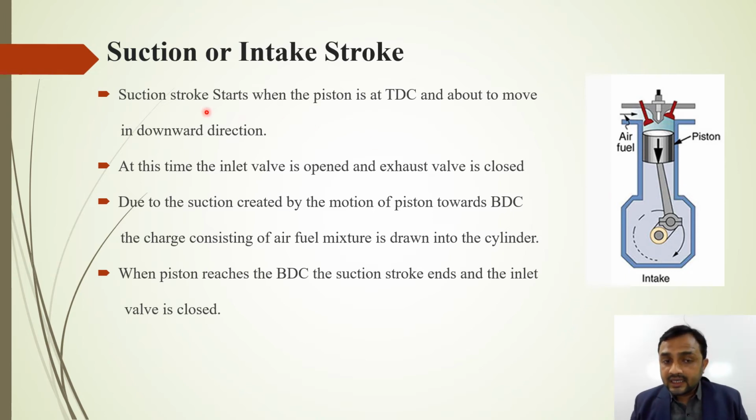In the suction stroke, the piston is at TDC, here, and about to move in the downward direction, towards the BDC. At this time the inlet valve is open, and the exhaust valve remains closed. This is the exhaust valve, closed during the suction or intake stroke. Third point: due to the suction created by the motion of the piston towards BDC, the charge consisting of air-fuel mixture is drawn into the cylinder.